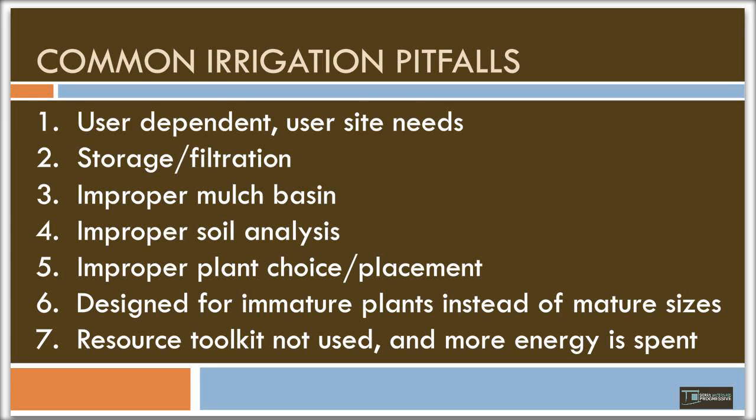People ask all the time, do I design the mulch basin and the sizing for the immature new plant that I'm planting or for mature sizes? You want to go ahead and plant it for the mature plant. It doesn't mean that you put your dispersal far away from the plant. You may have to change that over time. We have not seen that we've needed to change it at all. It was one of my major concerns when we started. The plants tend to really grow around and get used to where that water source is coming from.